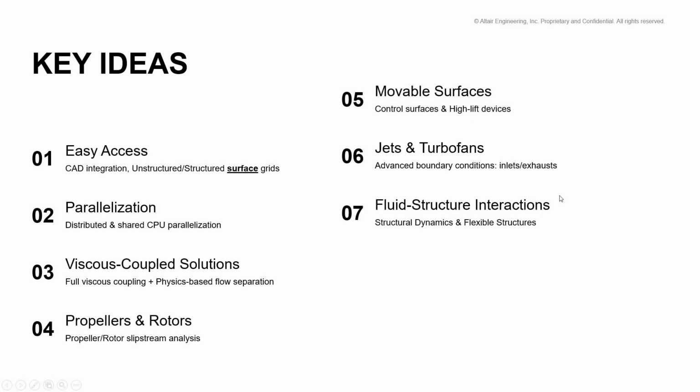Now coming to fluid structure interactions, I guess a lot of attention will come to this capability. Since volume mesh is not in play, morphing the geometry really comes down to morphing the surface mesh only. You can do static and dynamic modes both for wind gust analysis. Those kinds of capabilities are available right now with the rewrapped panel method in FlightStream.